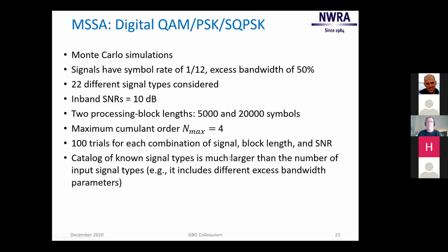Before we get to that, which is coming up quickly, let me just give you an idea of the kind of power that this technique can bring. So I'm doing some Monte Carlo simulations here. I'm generating signals over and over again and passing them through the MSSA and recording the results. So I'm looking at 22 different PSK and QAM signals. So BPSK, QPSK, 8 QAM, 16 QAM, 64 QAM, all the QAMs that you can think of, right? And they have an SNR of about 10 dB in band.